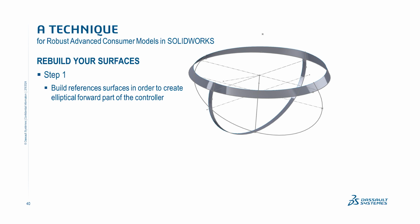So what I've done here is created two reference surfaces. And the way that I do this basically is I make them very simple. I create a couple of 3D sketch splines in one 3D sketch that are just simple lines. They're all equal. They reference tangent to adjacent geometry, and I use that as a boundary surface for the first direction, those four, and then the other one that they touch as a second direction.